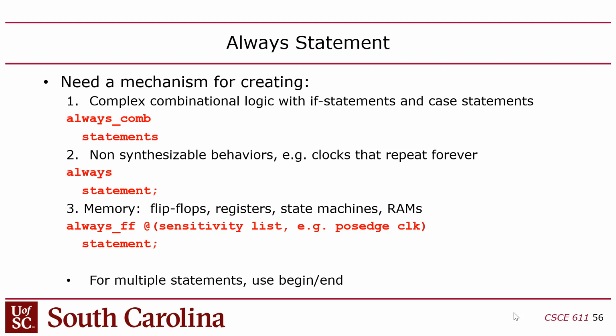The other problem with an assign is it's basically one line of code. I mean, you can put line breaks in there, so you can create this really big, long, nested ternary statement. But essentially, an assign statement is one statement. There's just one semicolon at the end, right? So everything you put in an assign statement has to be essentially one line of code, from the standpoint of the semicolon.